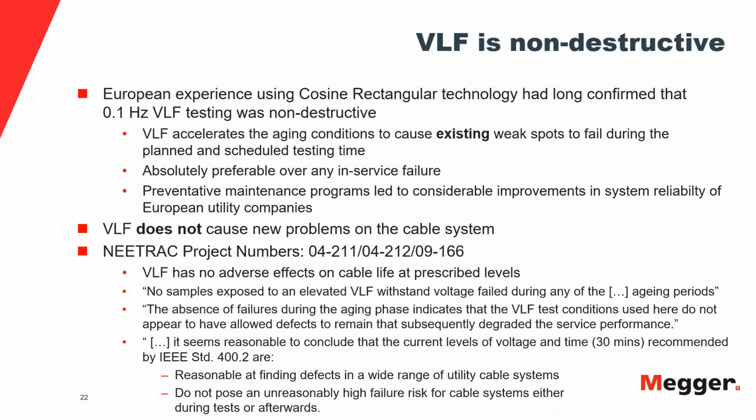And now, just to discuss this for a very brief moment, VLF is non-destructive, and what that means is, if you don't have faults in the cable, it won't fail the cable. The cable will pass. There are other hipot tests that have the sole intention of failing the cable. This is not one of these tests. It's not a step test.